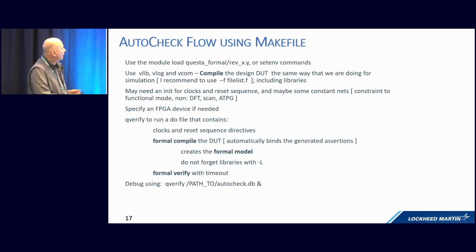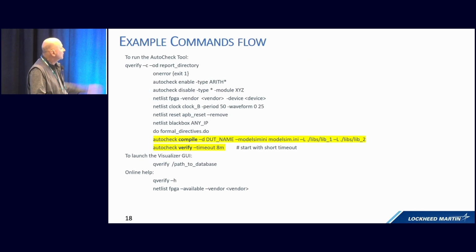It is good to set the clocks and the reset, although the tool most of the time infers the reset and the clocks correctly. This is an example of the commands, and again, I'm stressing here in yellow. Basically, there are two important commands, and then you can build upon that. First we do the vlog and vcom, then the AutoCheck compile and AutoCheck verify, and then we can start the GUI and see the results. Everything else can be built afterwards.